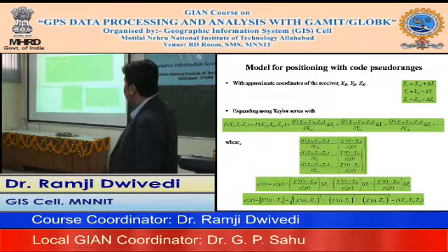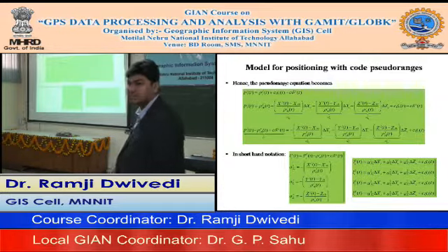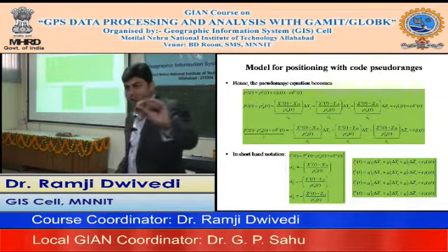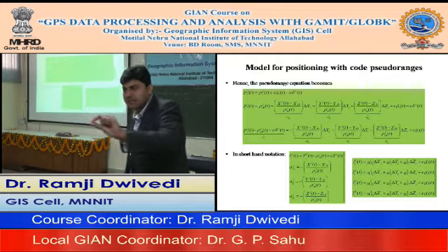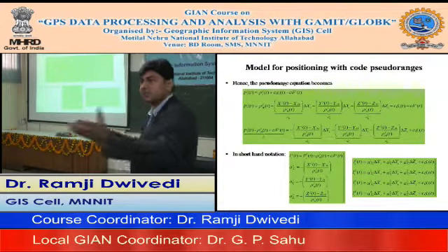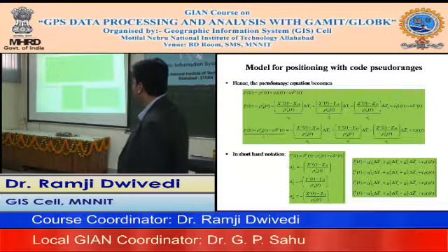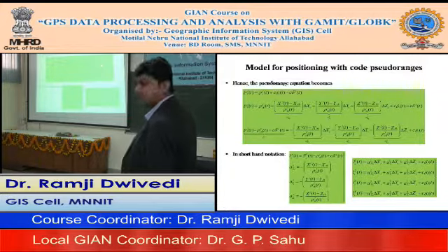We again rewrite those equations, the pseudo range measurement between ith and jth, rho ij naught, rho ijt at epoch t. Because at every epoch we are getting the measurement from the satellite. If you see the RINEX file, for every epoch you have certain measurements from those particular satellites in terms of pseudo ranges, code pseudo ranges, as well as the carrier phase measurements. So we are putting this value here from the previous slide. This is a little straightforward.